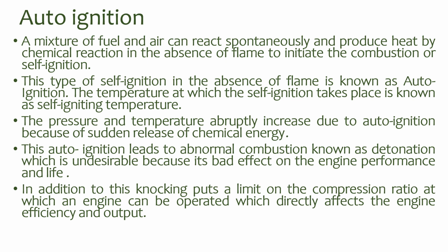This auto-ignition leads to abnormal combustion known as detonation or knocking, which is undesirable because of its bad effect on engine performance and life. In addition to this, knocking puts a limit on the compression ratio at which the engine can be operated, which directly affects the engine efficiency and output.